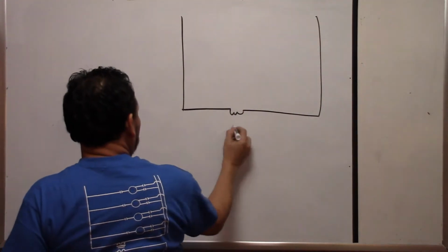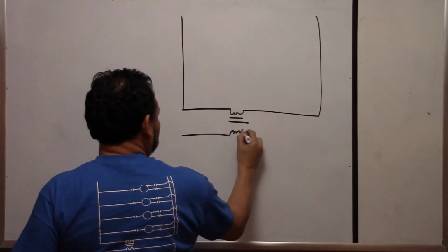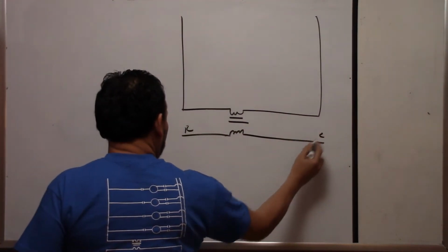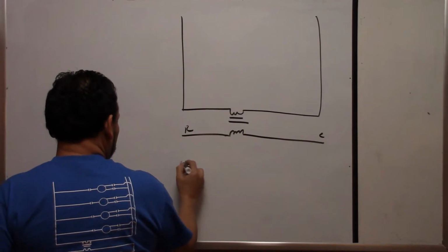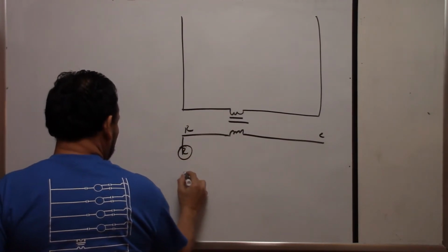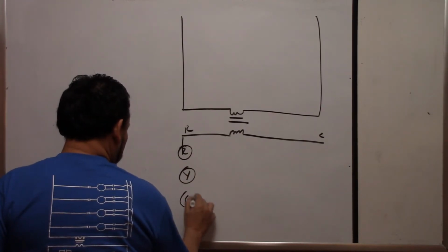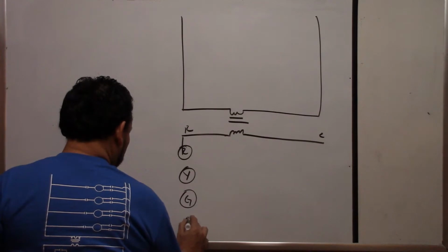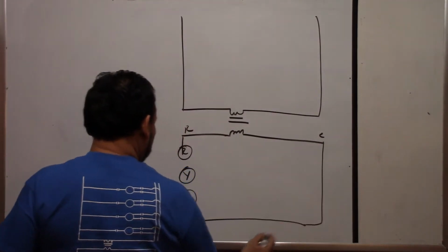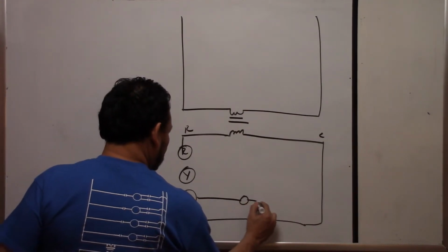If you remember, we have the step-down transformer. This is going to be R and common, and we're going to have R, Y1, and G, and common. Okay, if you remember, we're talking about common. And G, we also had the G, we have the coil.